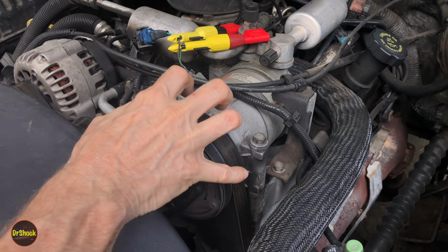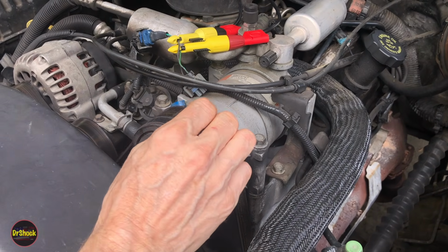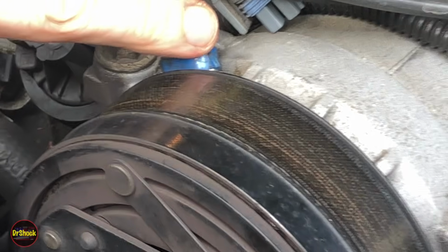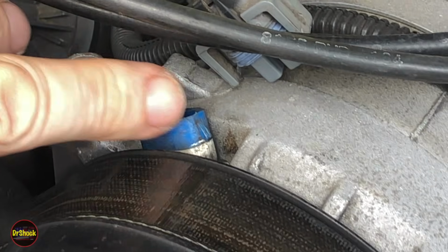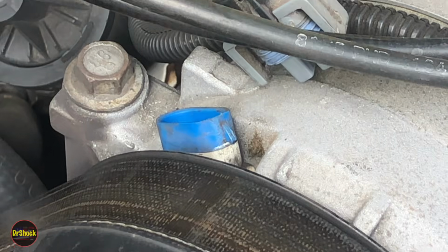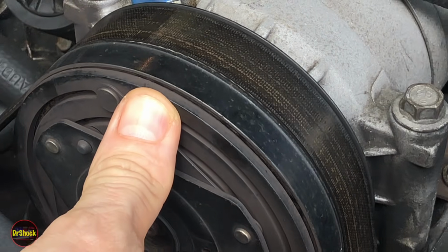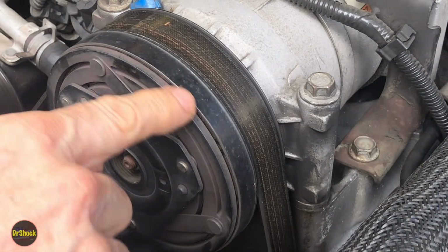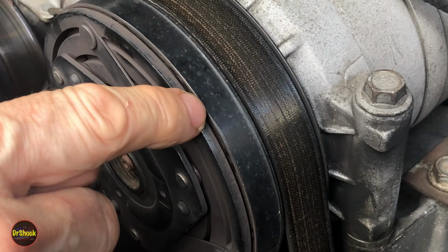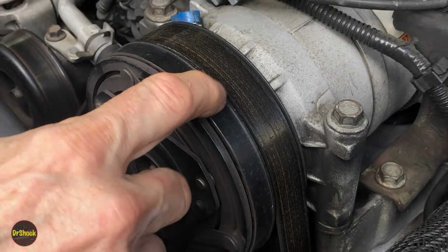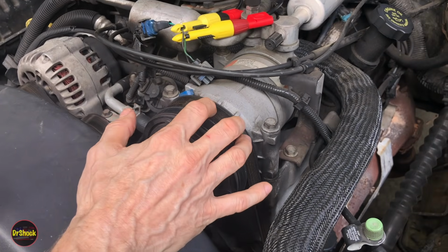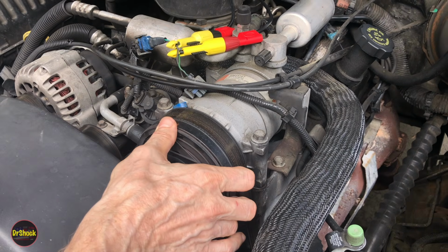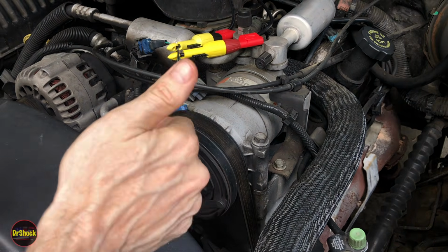So what's involved in the problem? Why do we have this problem? Well, this coil here for this electromagnet gets energized. And when current flows through this, that magnet pulls this clutch forward, like you saw in the previous clip. And then there's a friction fit between this clutch hub and an assembly here and the pulley assembly. That's what grabs the rotational force or energy of the belt and then actuates it so that it can turn the compressor shaft. That's how this whole thing works.